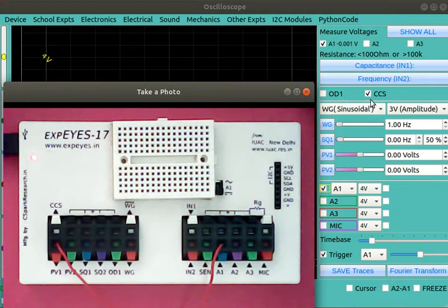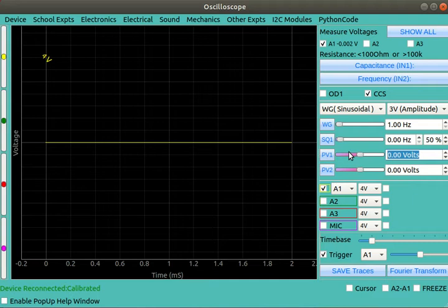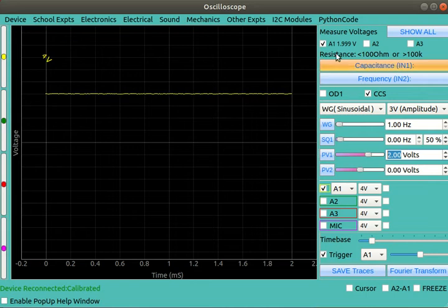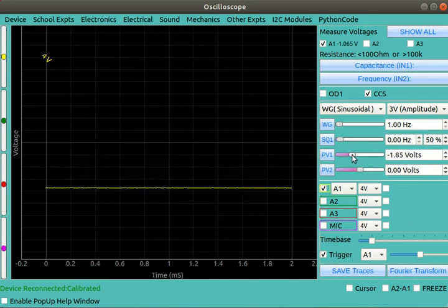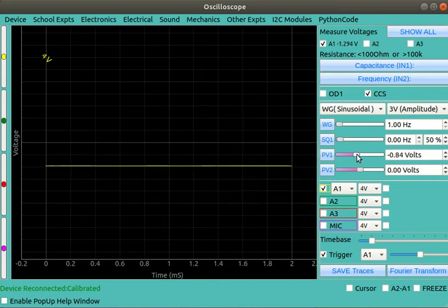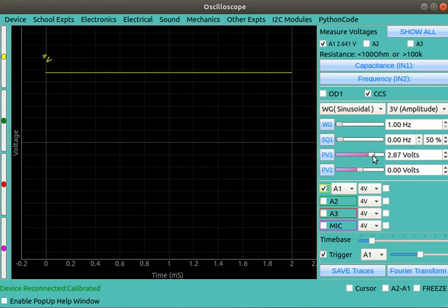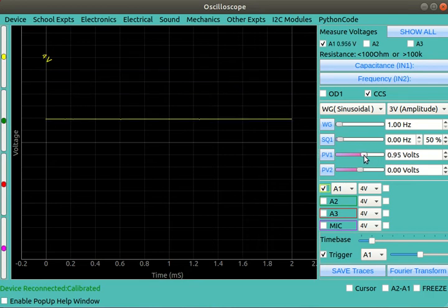So now you have to remember, whenever I click here, this picture will vanish because this window will come into the focus. So I'll just set the PV1 to some voltage. Say I set it to 2 volts. Setting it to 2 volts, and you can see here, right? This is becoming 2 volts. So I can also make changes using this slider here. Okay. This is also possible. When you change it, this voltage will change.